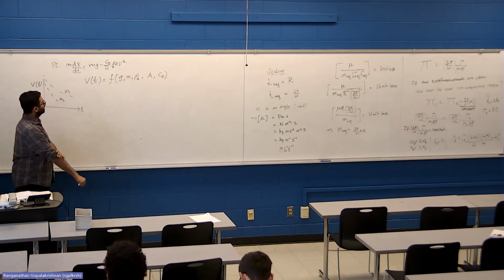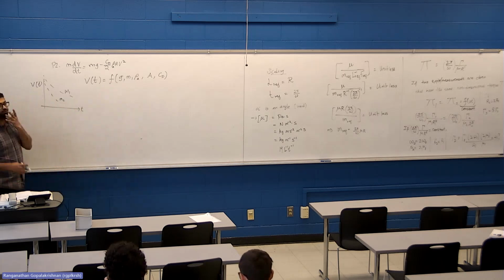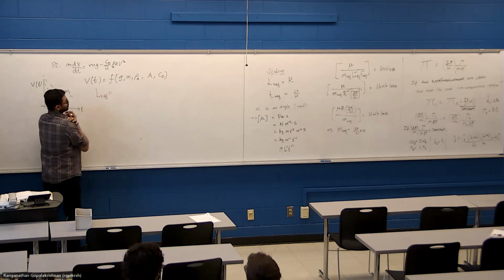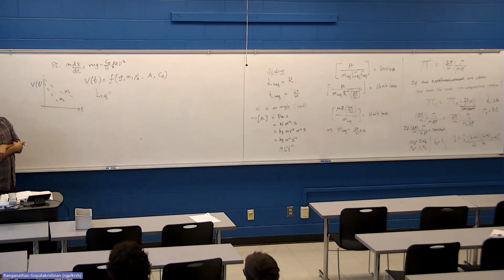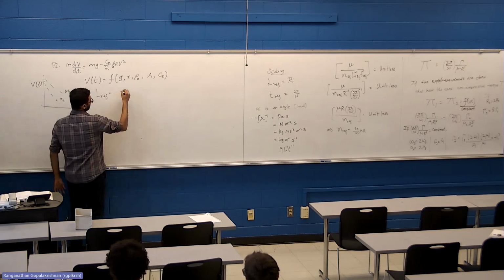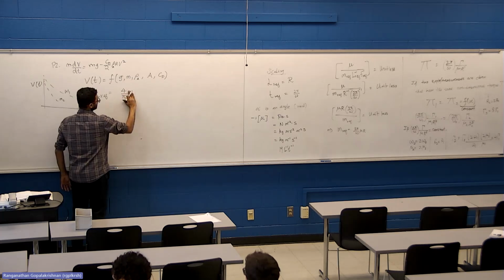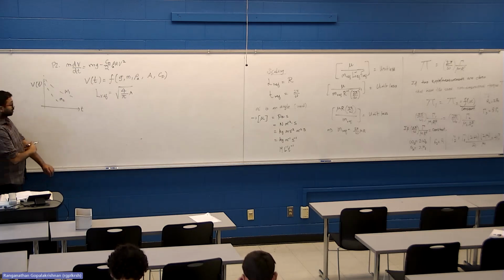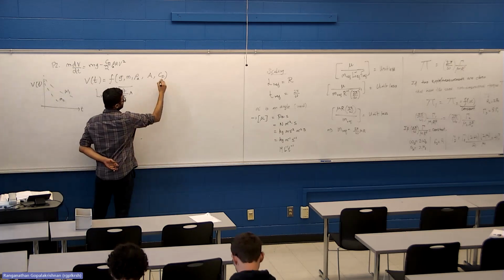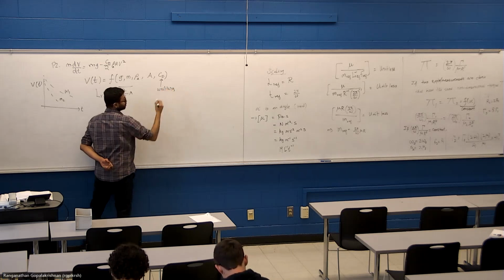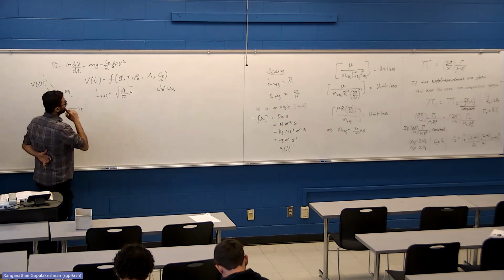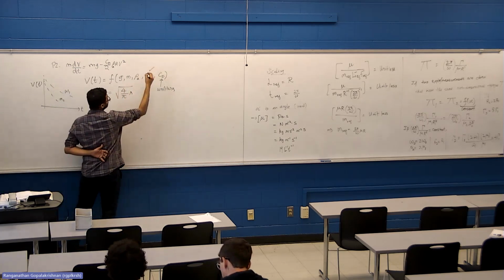Okay. So for this problem, what are good length scales to pick? What is a good reference length scale for this problem? Area. Sorry? Area. Area is not a length, so how will you make it into a length? Square root of area. So you can write square root of 4 times area over pi. That will give you diameter, right? So that's a good reference length. CD is unitless as it is. You don't have to non-dimensionalize that anymore. It's already non-dimensional.